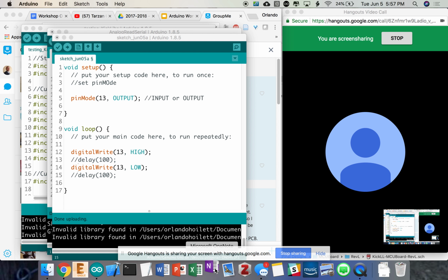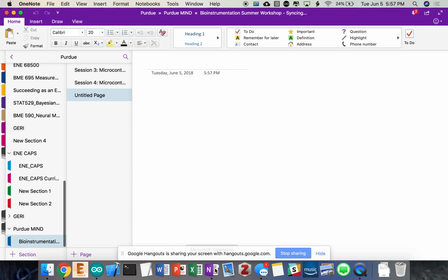Anyway, the keywords are pulse width, on time, off time, and duty cycle. Duty cycle is in percent, and it's just for how long it's on. So if it's on for half the time, we say it has a 50% duty cycle. If it's on for a quarter of the time, we say it has a 25% duty cycle. On time is just how long it's on, generally in seconds. Off time is just how long it's off, also in seconds. But typically, the words you'll hear are more likely duty cycles. So someone says, set this at 50% duty cycle, set this at 25% duty cycle, et cetera.